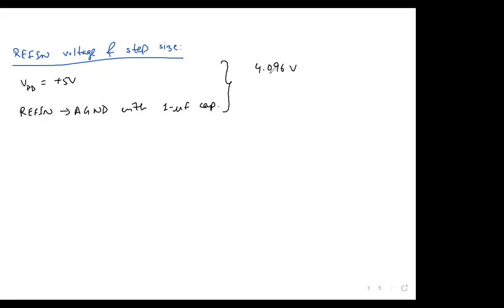All right. So if your reference voltage is 4.096 volt, then can you calculate the step size? What will be the step size for this particular case? Is there anyone who can remember? How do we find it? Tell me. Divided by 256. Good. 4.096 divided by 256, which will give you 16 millivolt as the step size. And I will not be discussing again why and how we got 256.